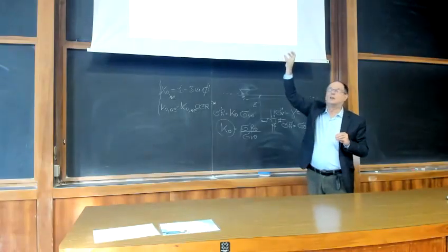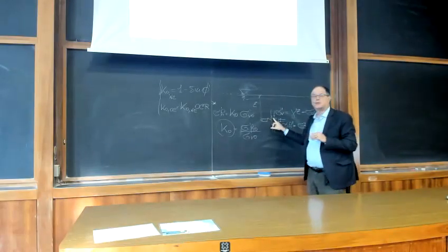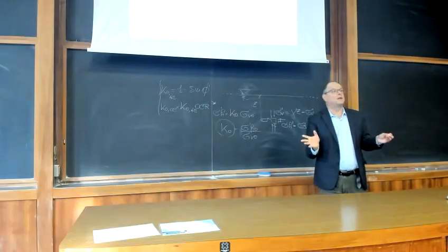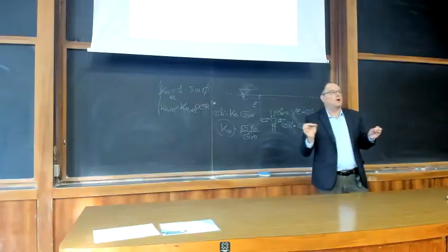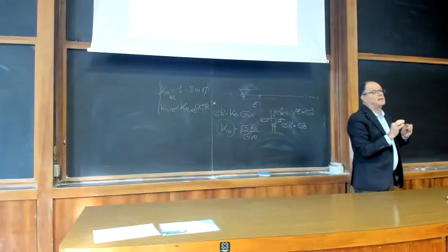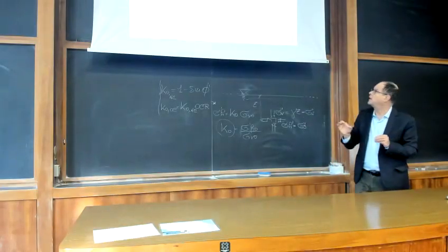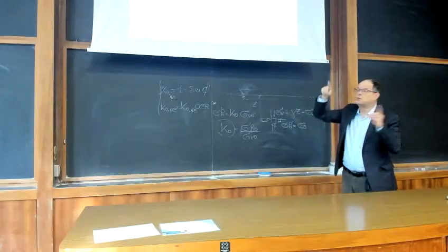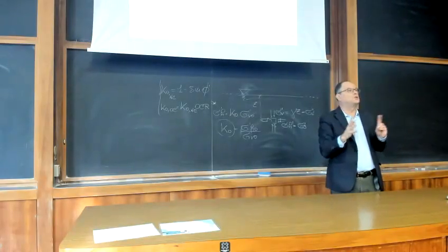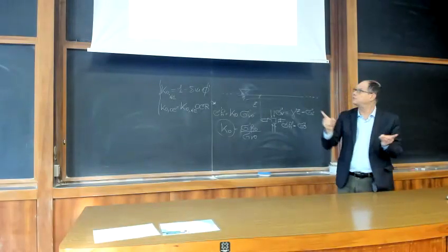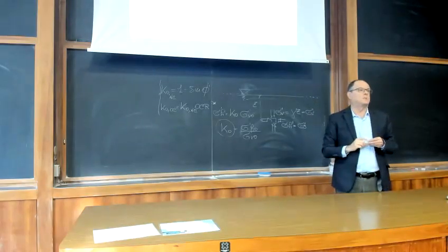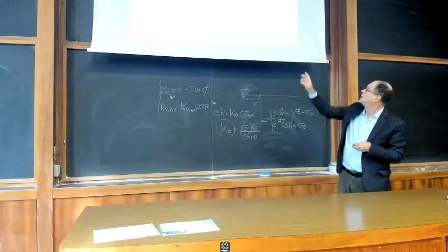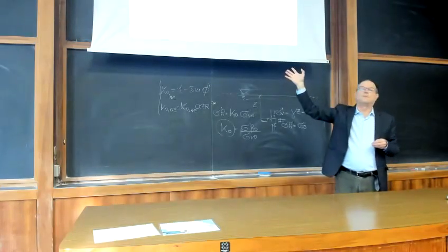Once you define your vertical stress, and the vertical stress is defined by vertical equilibrium, then the condition of being tangent to the limit line makes the two circles statically determined. There are only two circles going through your vertical stress, sigma dash V naught, that are tangent to that line.